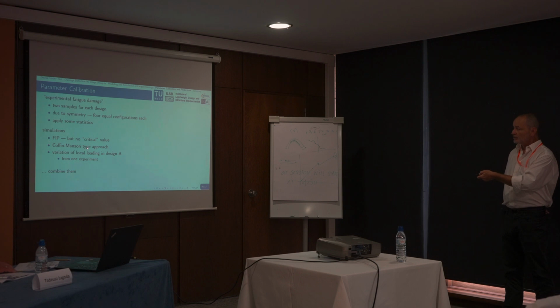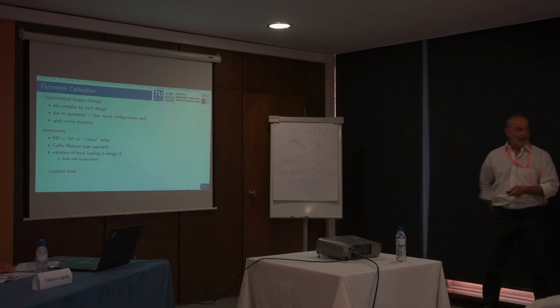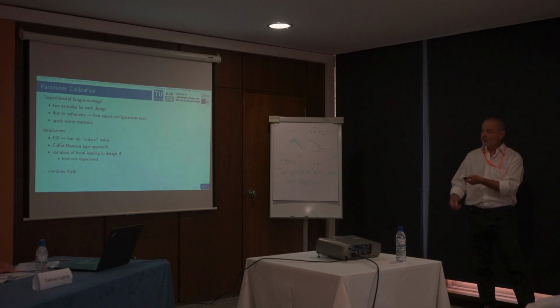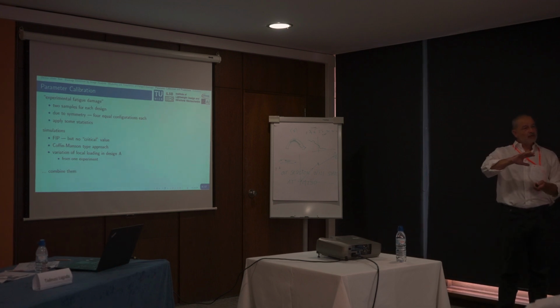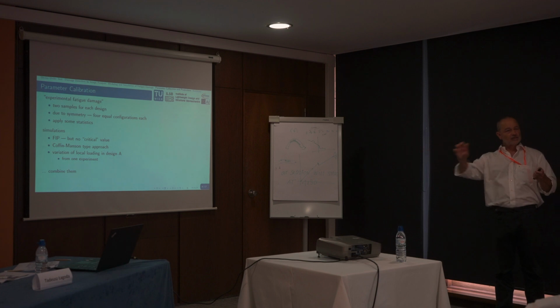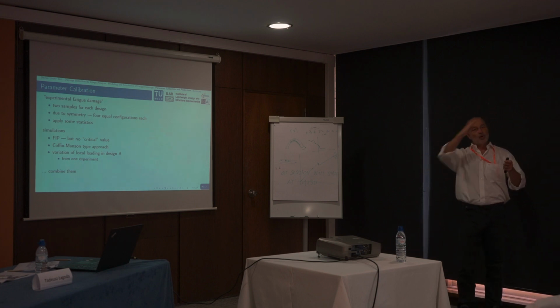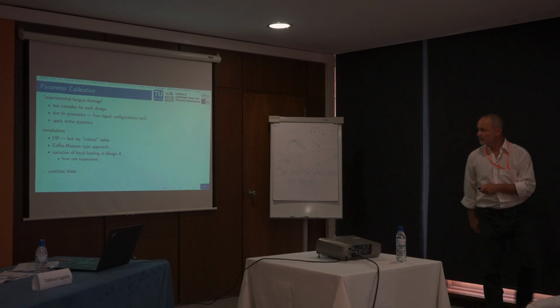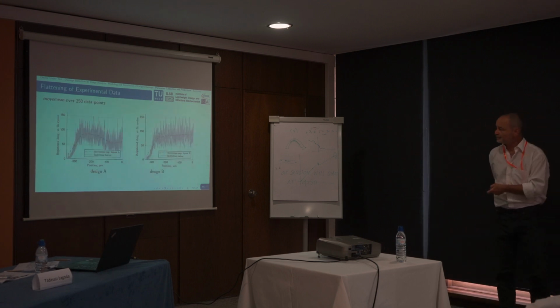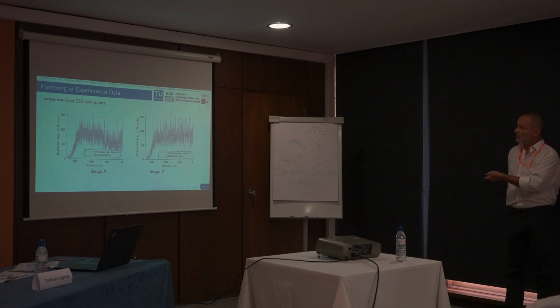And we consider this then in terms of a Coffin-Manson low cycle fatigue approach. And we consider now the design A. And the interesting thing here, or the good thing is, we have an experiment where we have locally different loading situations. So we have one experiment which gives us, let's say, different points in the fatigue curve. That's a nice thing.